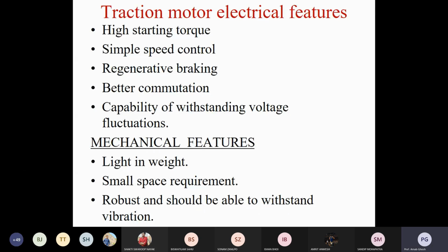If both are rotating in the same direction, both anti-clockwise, then you need to change the terminals of the driving motor. Then both will rotate in the same direction. Then you have to start both motors. Then you need to control the armature of the test motor, up to the base speed.